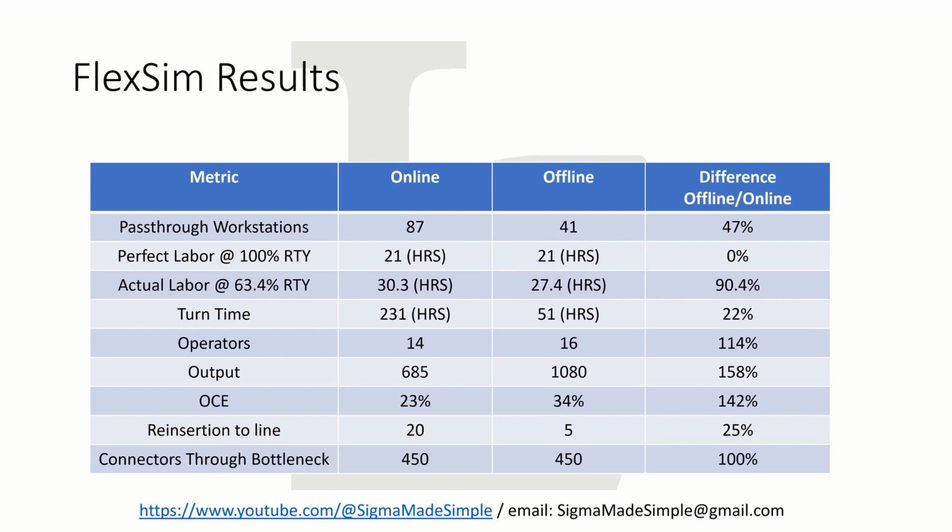As far as the decision on if you add workstations to a line or convert one line to support more than one line, it's not always clear. When you convert a line to a recovery area, this area will be fewer in personnel, as it only has to deal with the workstations involved in the rework loops.